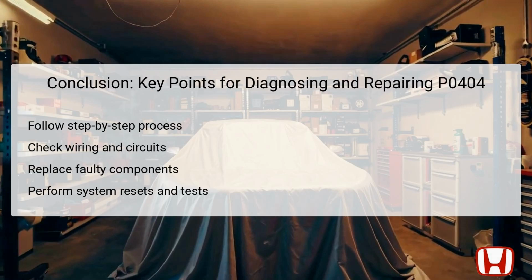In conclusion, troubleshooting the P0404 code involves a systematic approach that includes verifying the fault, checking wiring integrity, testing sensors and connectors, cleaning ports, and replacing defective parts. Using diagnostic tools like the Honda HDS scan system ensures accurate interpretation of results and guides appropriate repairs. Always confirm the repair effectiveness with tests and system status monitoring before concluding.